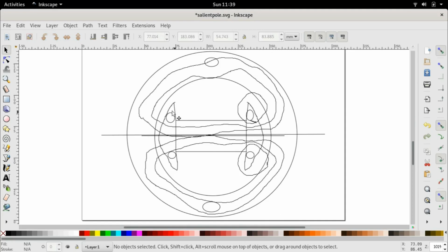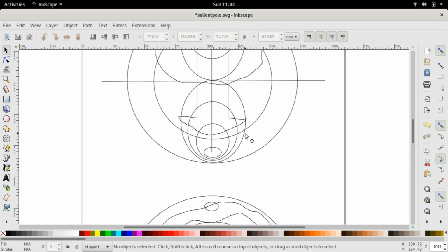The reason is that it is the rotor that is producing this flux to begin with. So it is very clear that in the case of a salient pole rotor, if the rotor itself is excited, there is no difference to the flux produced by the rotor as the rotor rotates. And if the flux produced by the rotor is independent of the rotor angle, then one can say that the self-inductance of the rotor is also independent of the rotor angle. So it is quite a surprising observation here as compared to here.